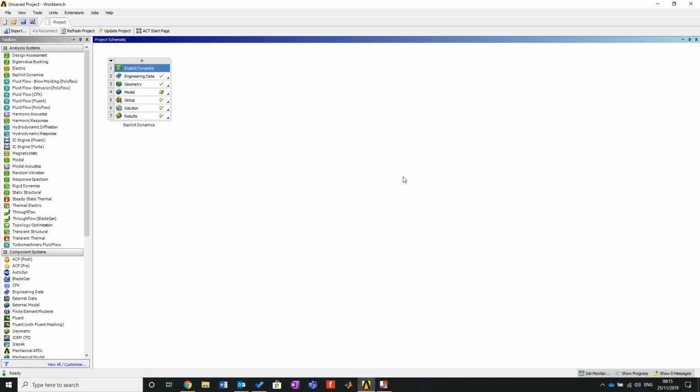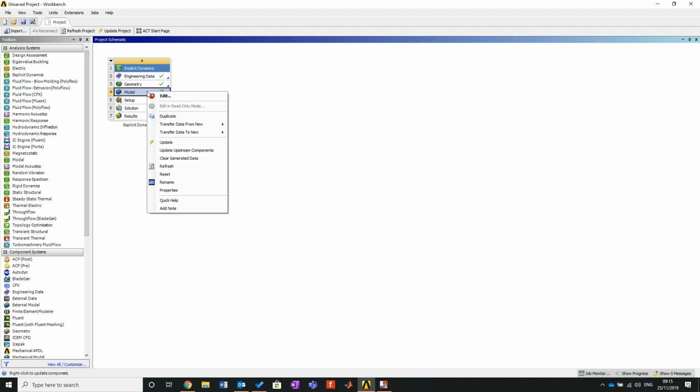I mean, arguably, a student said a couple of weeks ago, if a bullet's hitting, is it wise to do symmetry on it? Ideally, we could presume that both sides will deform as much as each other. But really, he does have a point. Because this is an idealistic state, because the material is equal all the way through, arguably it's almost pointless doing the whole thing. But we're going to do the whole thing for this. When we get to the end of this, I'll show you how to apply symmetry, and you can run it again to your heart's content. So let's get back into it, and let's get this solved.